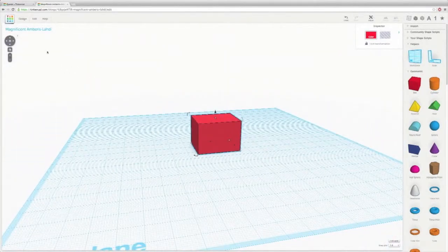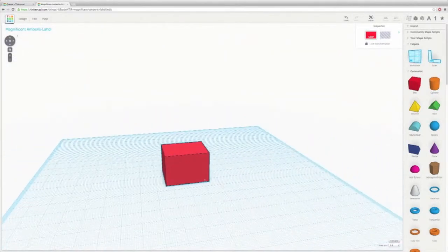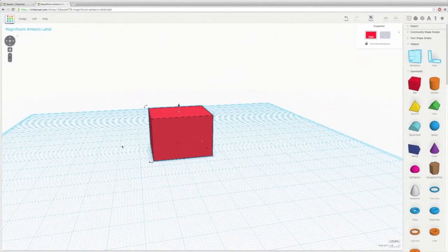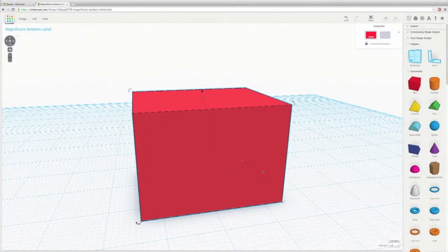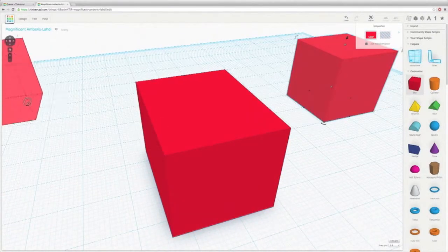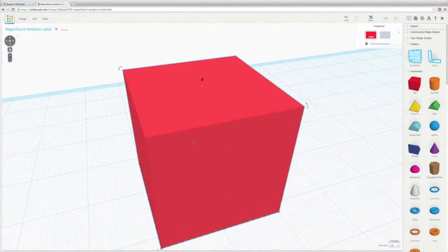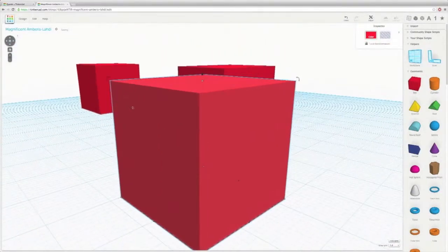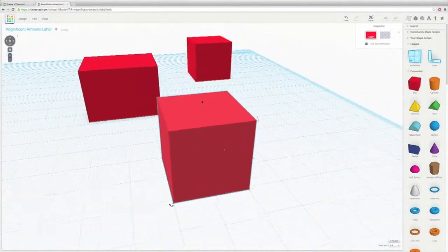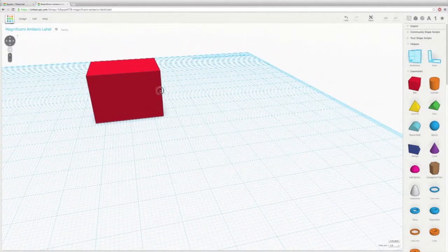Alright, so I don't use this top left corner at all, I just use the mouse, it's much easier. When you have an object selected, you can hit F and it will focus onto the object. So if I had several different objects, I could select one, press F, focus on it, navigate around, select another, press F, and very quickly rotate between different objects.